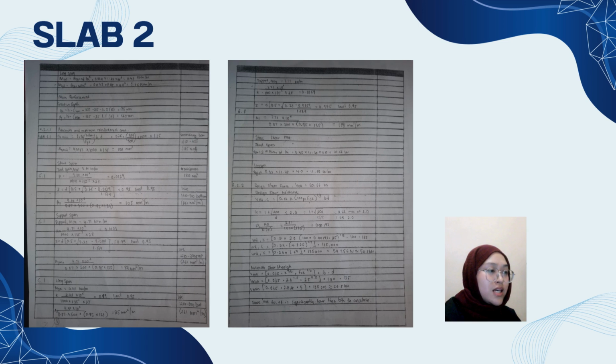For all these sections, the calculated steel area was actually lower than our minimum requirement. Therefore, to be safe and comply with regulation, we decide to use H10-300 bars, which provide an actual area of 261. This covers all our bending requirements comfortably.